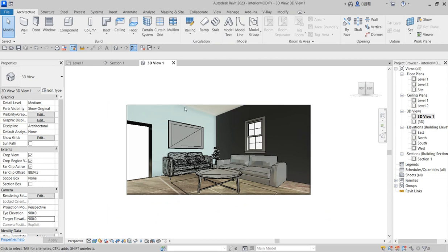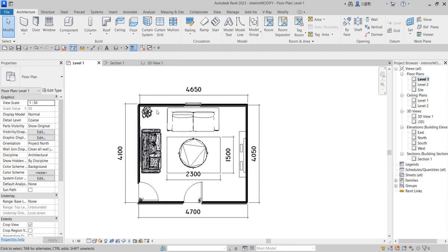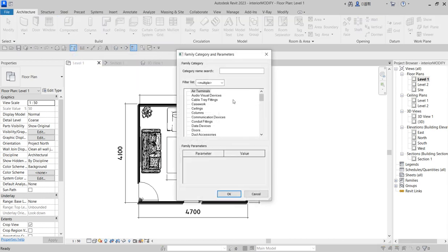Now, because we are seeing the ceiling, we want to create a coping around this place. At the same time, work on this wall, because you cannot leave the wall empty, and do some things about this place. So that is how interior works. So what we do now, you click on the floor plan. So you have the floor plan. Go to your component. From the component, model in place, I want to create coping around the edges of that ceiling.